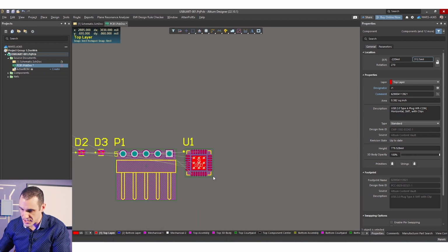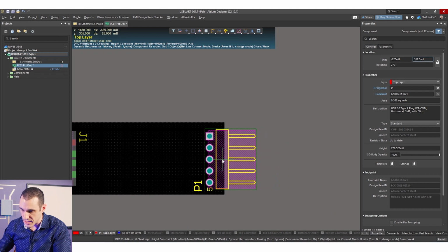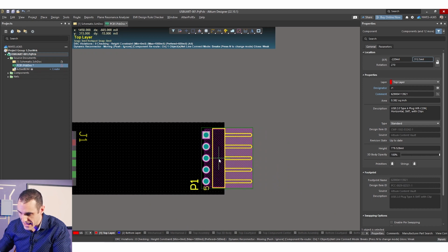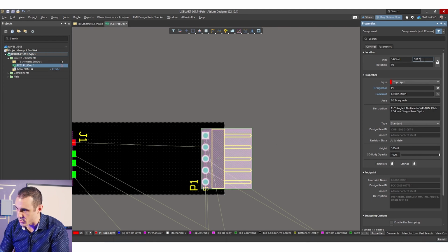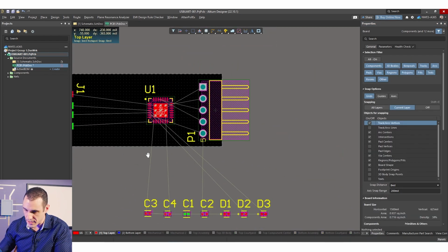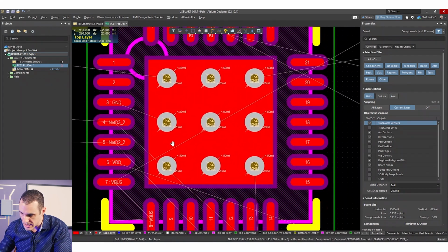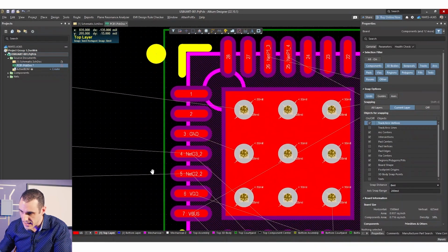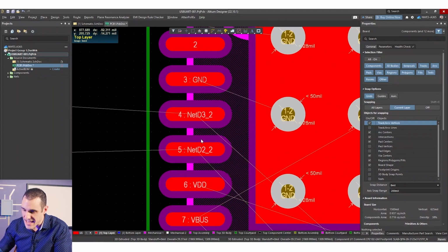And then we'll wanna do the same for the pin header, so that way we have a nice, clean looking layout. The pin header, we're gonna set it just a little bit back from the edge. We'll do the same thing here. So you can see it's already set up very close to the required 312.5 mils. So those are our connectors. We want to start placing everything in the layout, and we want to make sure that we orient the pins appropriately to drag in the data as well as the bus connections. Now you can see here already, they're not named properly necessarily for data lines, but you can see right here, we have our data lines coming in right here.